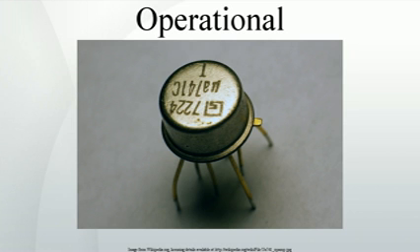It had 2 major innovations. Its input stage used a long-tailed triode pair with loads matched to reduce drift in the output and, far more importantly, it was the first op-amp designed to have 2 inputs, one inverting, the other non-inverting. The differential input made a whole range of new functionality possible, but it would not be used for a long time due to the rise of the chopper-stabilized amplifier.